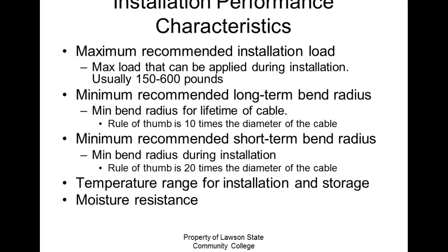Minimum short-term bend radius is 20 times the diameter of the cable. So if you are pulling it, this would be a short-term bend. Then we would look at 20 times the diameter of the cable. Long-term bends, we could go back down to 10. Everybody understand that? That makes sense. Any questions there?